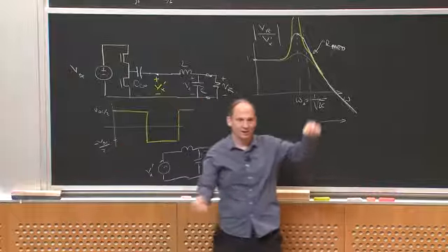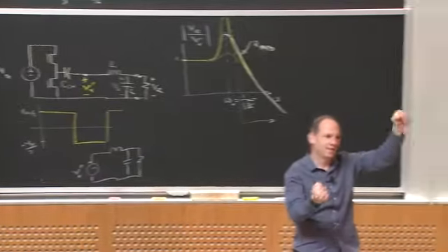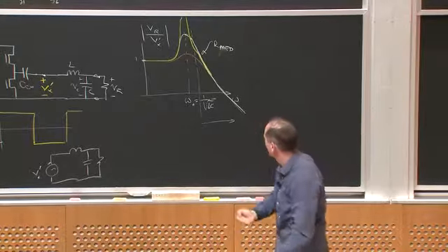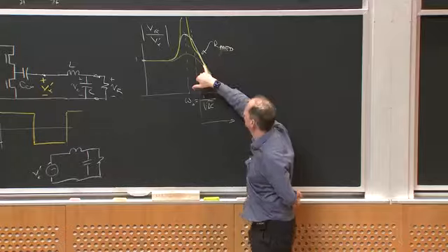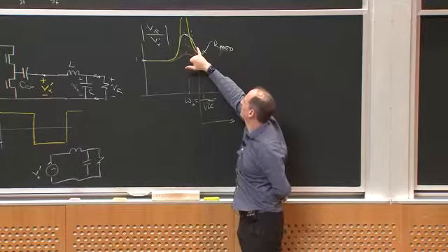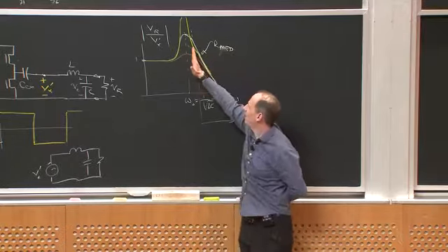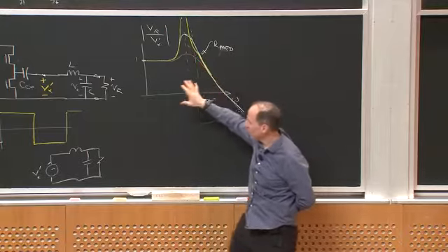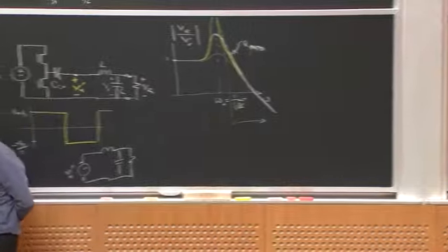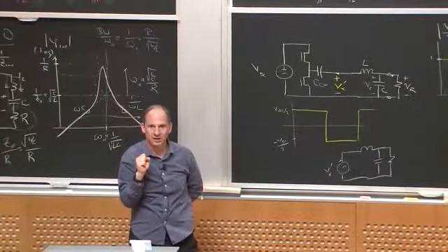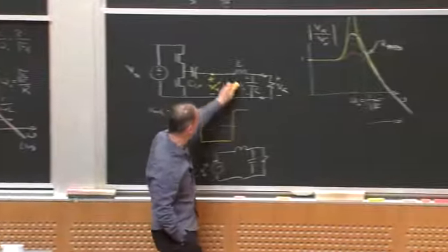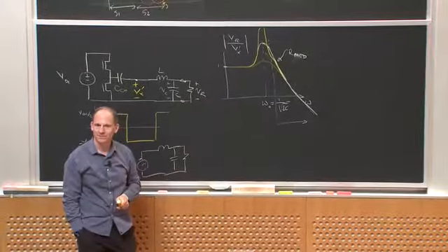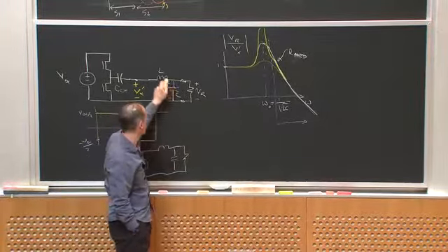Eventually, the fluorescent lamp breaks over, and then you've ionized the gas, and then it looks like a resistor, but not a huge resistor, a small resistor. And I go from the green curve maybe down to the white or orange curve, and then I can modulate the amount of power in the light by moving frequency. So this kind of network would be at the core of many fluorescent lamp ballast drivers. And we're taking advantage of the resonant voltage gain I can get from this high Q tank. It's particularly high Q when the lamp isn't struck. So sometimes I want the big voltage, even though I have to rate this capacitor and inductor for it.